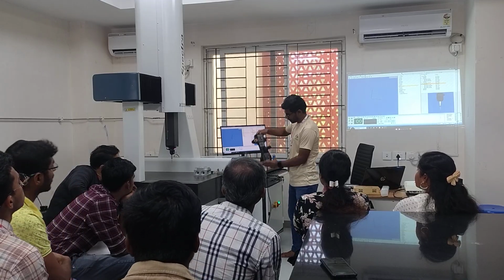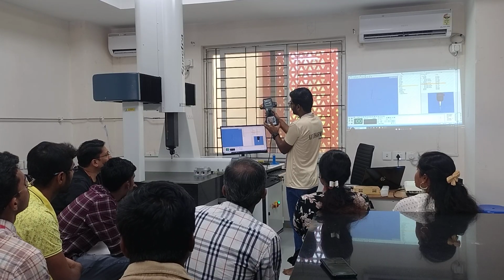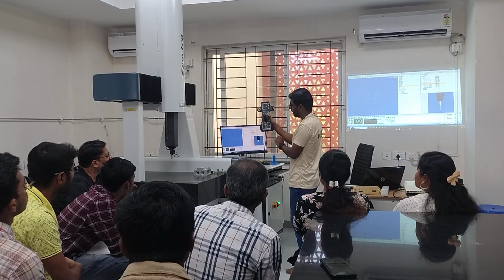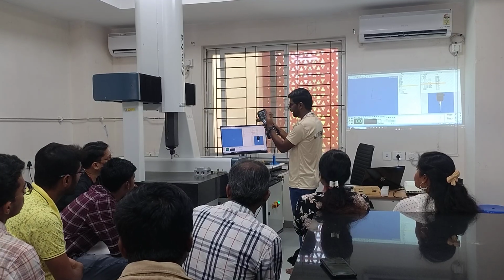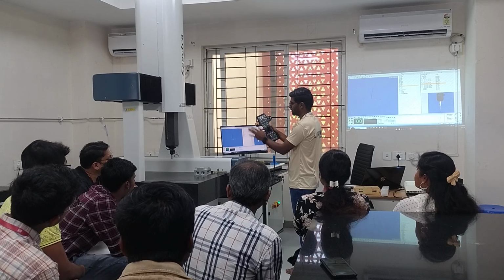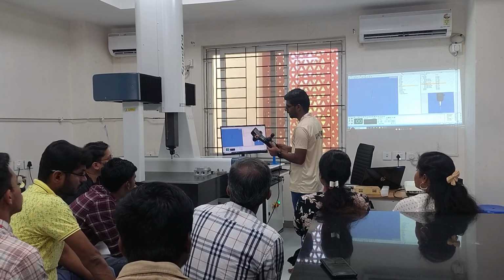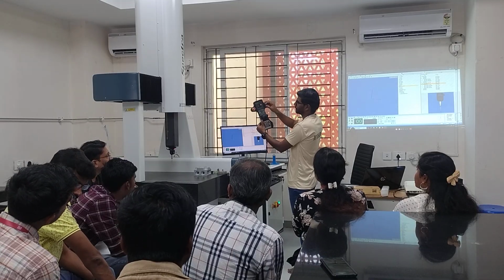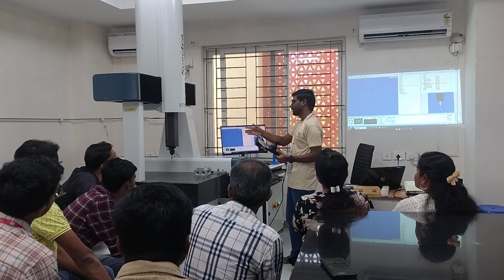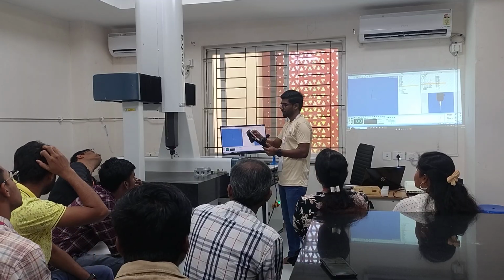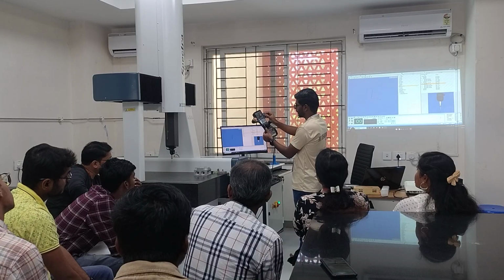So teach pendant, I'll explain the basics. This is the engage, disengage button. If I click on disengage, this MCU becomes off and whatever we do, it will not be translated here. If you want to engage it, I'll have to click on this again. This is the emergency button. If something goes wrong, just click on emergency. The machine will stop in as-is situation. This is speed override. If you want to increase the speed of its movement, it has a speed of around 300 to 600 mm per second. You can give it the maximum, say 600 mm per second, and we can just translate it.